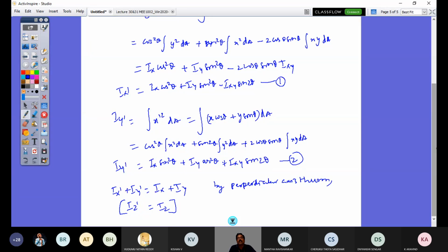A similar, analogous study you are going to do in your strength of materials course as well, looking at principal stresses and the relationship between shear stresses and normal stresses. You would define something called the principal planes, the ones where shear stresses are zero.